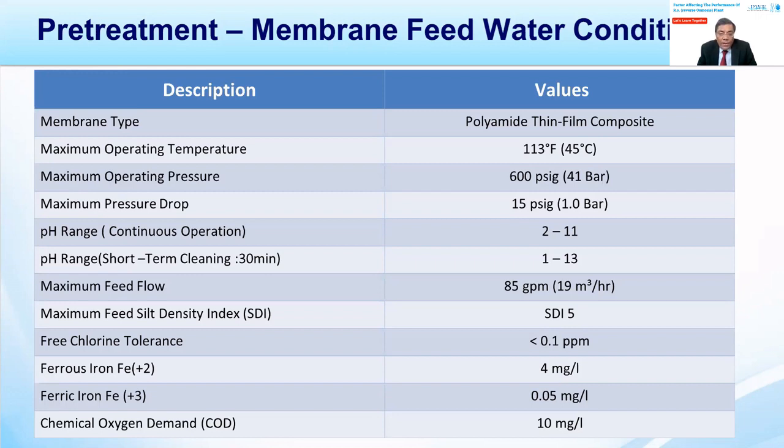But normally, we have observed that with up to 100 milligrams per liter COD, recycling plants, especially UF, are operating, and at the outlet of UF, the COD at the feed of the RO plant is around less than 50. But it all depends upon your designer and how well he designed the pre-treatment to achieve these values or come close to them for smooth operation of the plant.